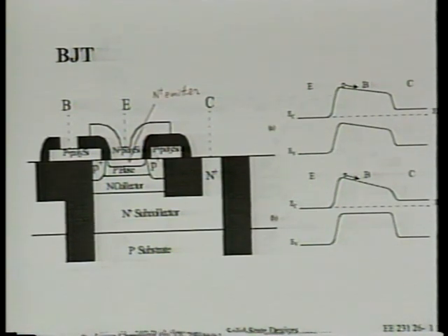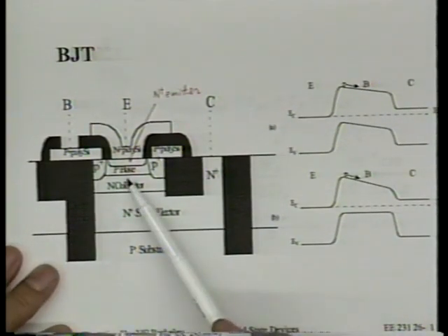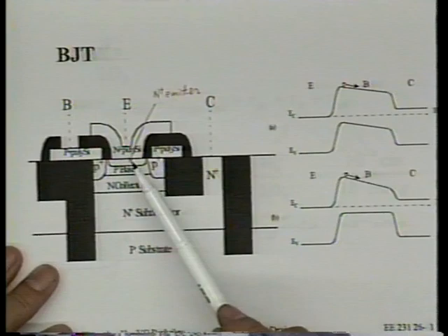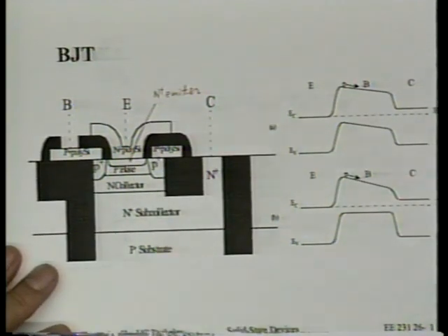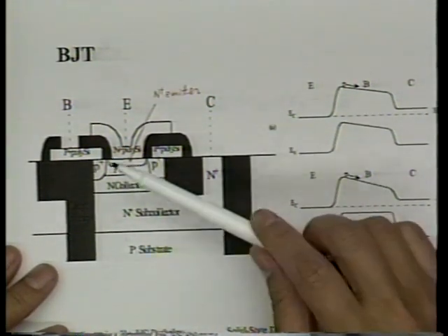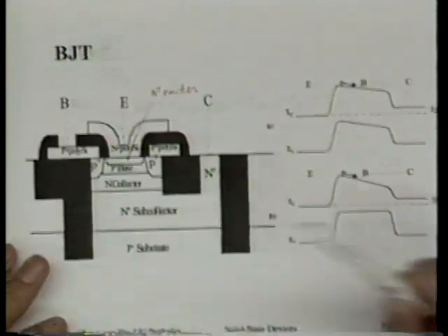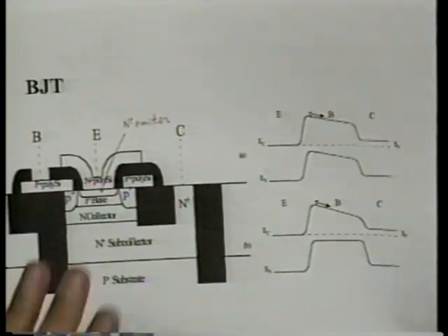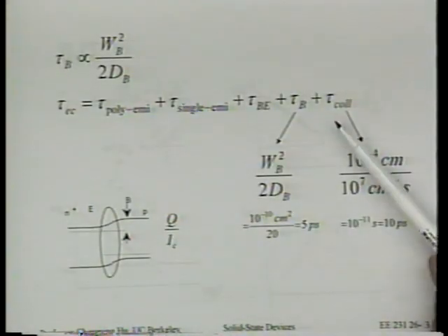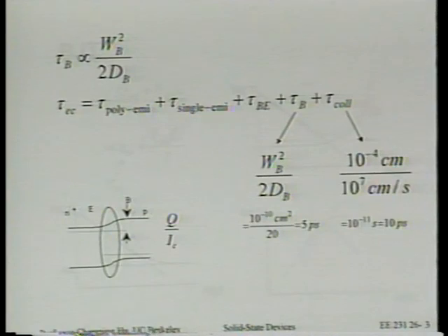And how do you make a large breakdown voltage for a PN junction? You insert a layer with light doping, right? So for this reason, we have a very thin emitter, a very thin base, and a thick collector. So the transit time through that is actually quite significant, and in fact, that also becomes a function of current. I'll get to that. So remember, this transit time going through the collector is a problem.